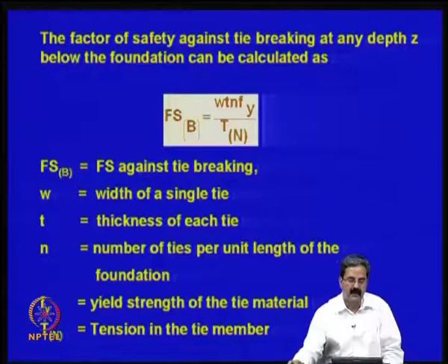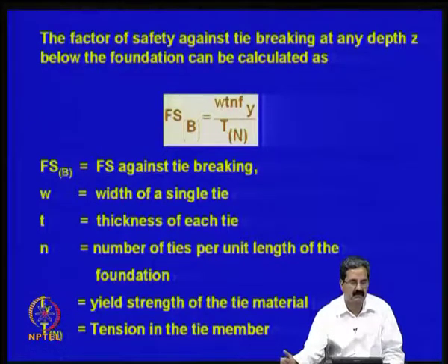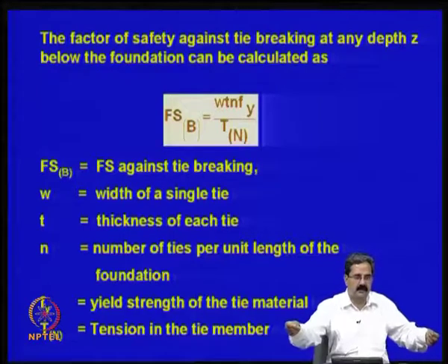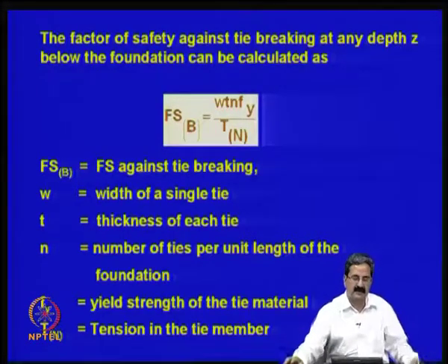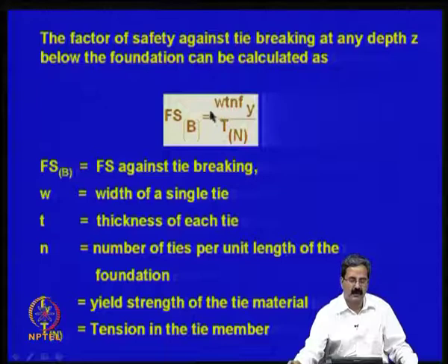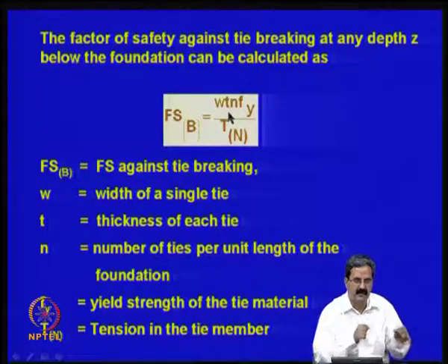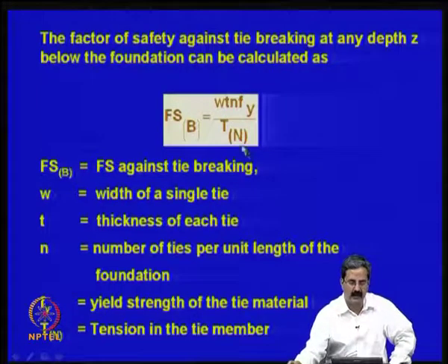Then you express the tensile force also in terms of the meter length. You take some 1 meter strip, 1 meter with some thickness, then you will have the total WT, and then you test the same 1 meter strip. So, you will get the spacing, and you will get the factor of safety, right.